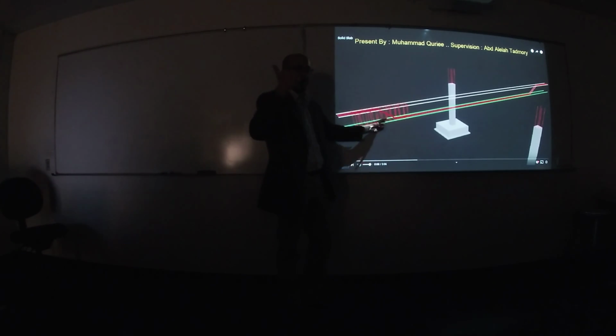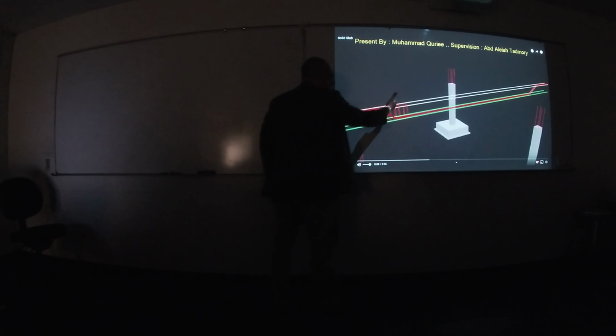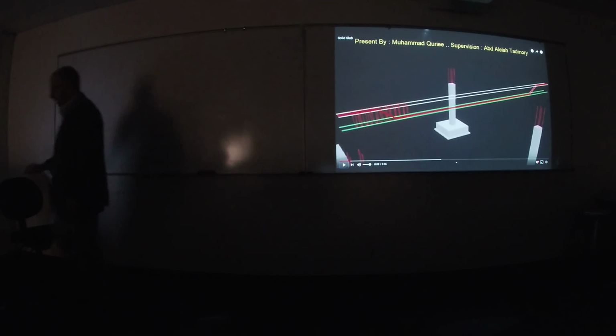Do you remember last time? We can expect shear failure with an inclined angle, 45 degrees here. So you place your steel reinforcement perpendicular to the expected crack to close this crack. Anyway, keep going.